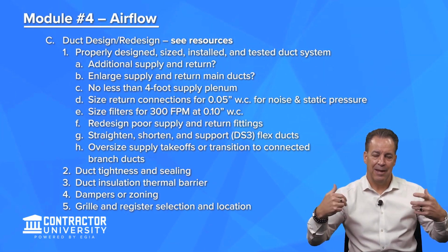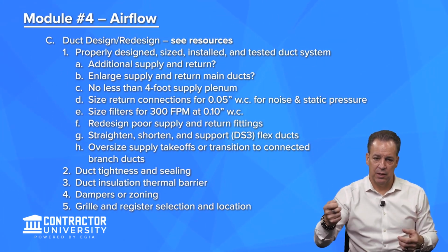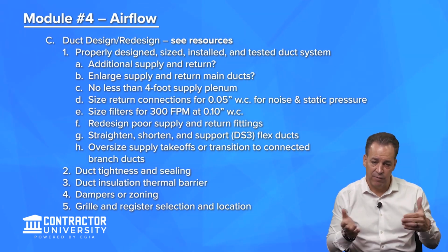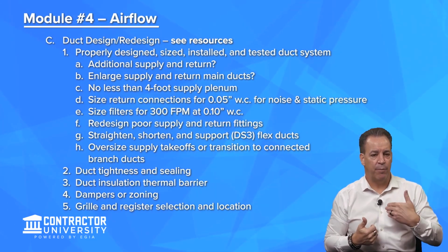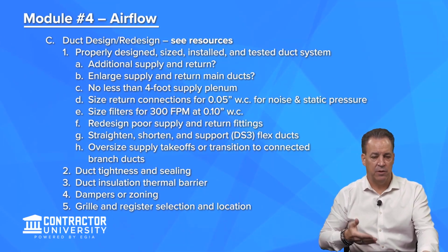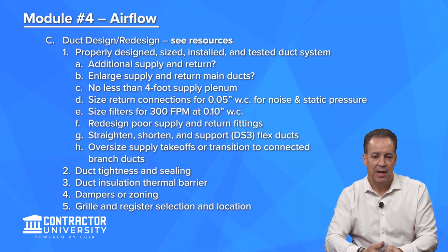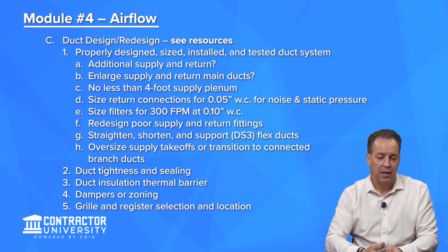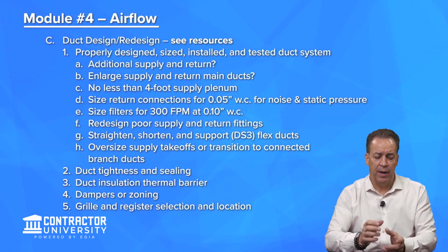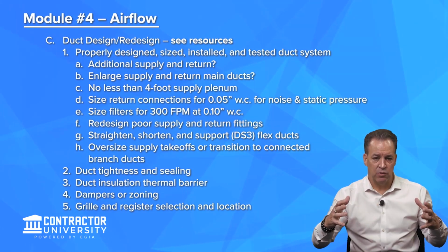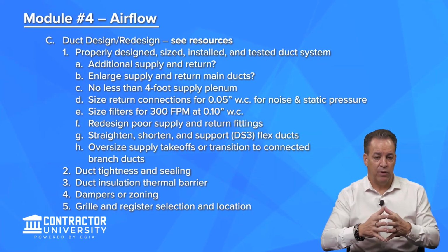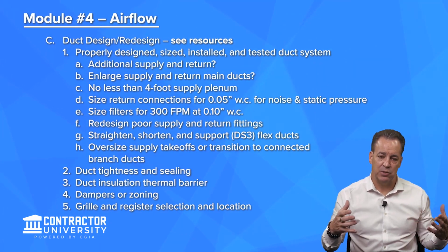Like I said to you a little bit earlier, registers are not designed to be closed. You can fine tune them a little bit to direct the airflow off the occupants because you never want to blow air on the people themselves, and you'll see that in one of the documents that I shared with you, 17 ways to improve duct systems. But those registers also could be noisy. And again, when you make them less restrictive, they become less noisy.